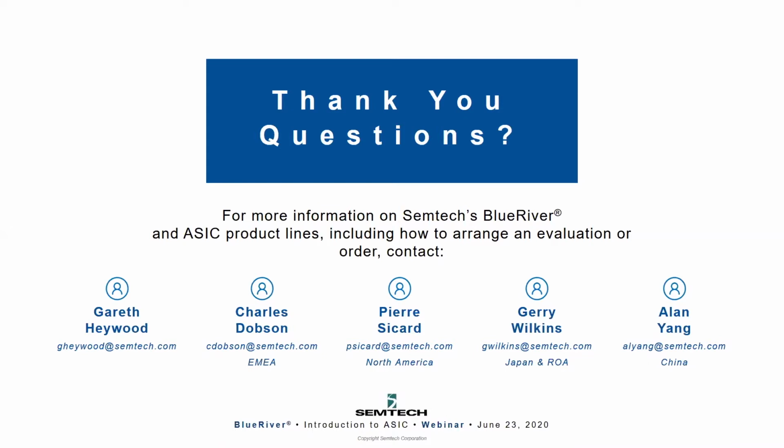Great. This next question is actually about 10 gig, since you mentioned that. Dario Pagano asks, is the 10 gigabit Ethernet PHY integrated directly into the ASIC? No, in terms of the 10 gig copper PHY, we actually rely on a third-party external PHY for that. And the reason we do that is we want to be fully IEEE compliant.